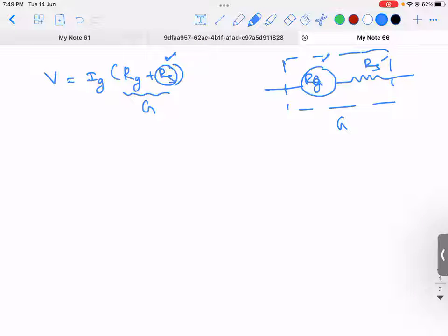So that's what you need to keep in mind. That is the reason I showed all those calculations. Finally, what they're saying is I want my voltmeter to measure N times V. For example, initially the voltmeter was measuring 5 volt. Let's say I want to increase it to 20 volt, which is 4 times the initial value. Then using the same galvanometer, what changes do I need to make? Then IG would have been V divided by G, where this G is the resistance of the voltmeter, not the galvanometer.